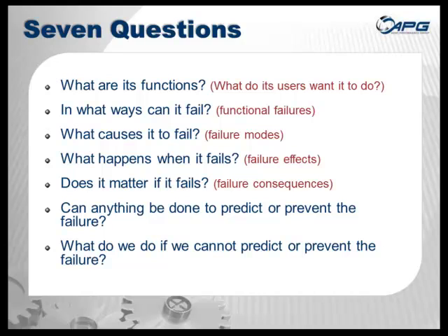What can be done to understand that failure mode before it occurs or when it's in the process of occurring? And even if something can be done, what is the value, the return on investment for the maintenance policy back to the business? Often we'll find that tasks that actually can be done, in many cases, shouldn't be done. They are not optimal. Sometimes the failure is actually a cheaper solution. If that's the case, and that particular suggested task is either not technically feasible or worth doing, we move to the seventh question, which simply offers up an opportunity for the participants to throw forward an idea. It may end right there in a no scheduled maintenance suggestion, or it may also provide a secondary action where a redesign may help to alleviate or reduce the consequences of those failures, and that's that output associated with one-time changes.